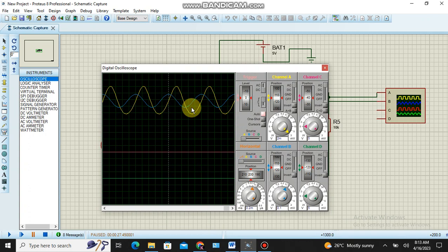The amplitude of the output signal is maximum compared with the input, and also the phase difference is exactly 180 degrees at the center of the bandwidth. Otherwise, at the flat response bandwidth, we can get the exact waveform. In the lower sideband and upper sideband, a little distortion will occur.